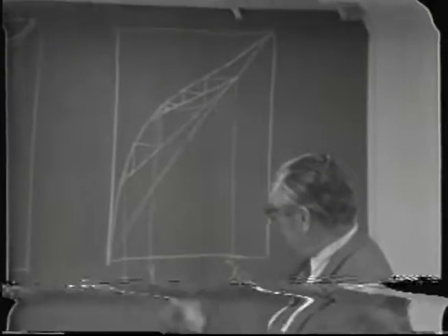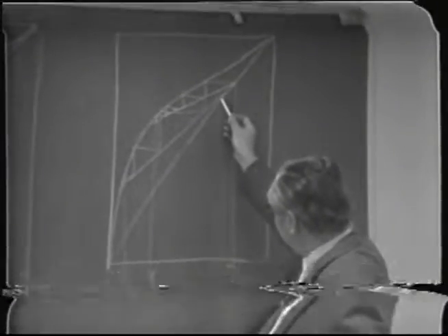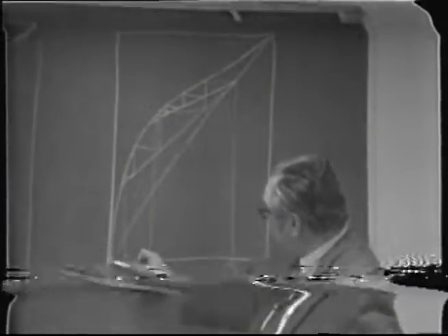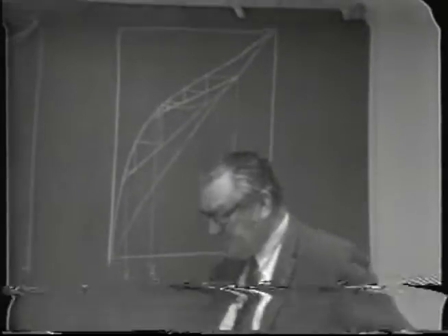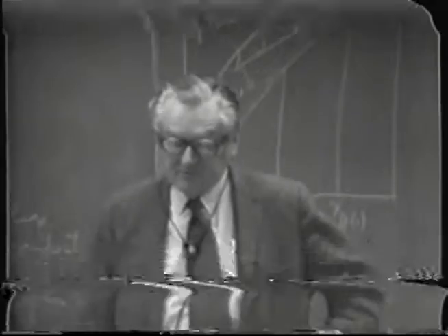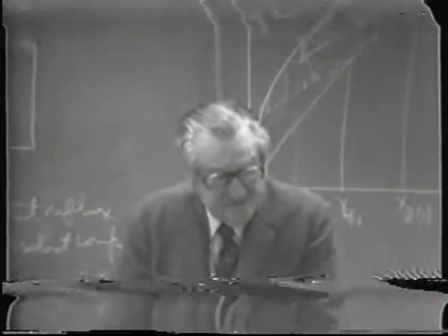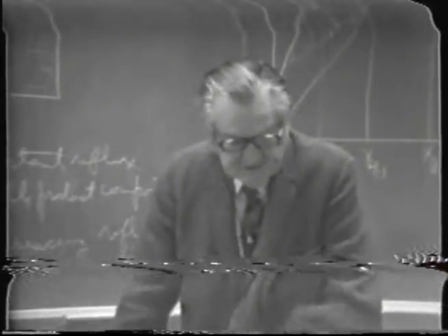Of course, it should be apparent that at some value here, you reach the minimum concentration in the liquid in the pot which would be able to produce that concentration even at infinite reflux ratio, that is, total reflux.